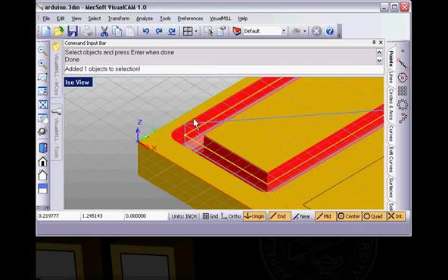If I click off to the side a little bit, this orange line indicates this is my original drawing line. So notice an engraving piece puts half of the cutter on each side of the engraving line. So if I've drawn a box 2 inches by 2 inches and engrave around it, I end up with a box on the inside that is actually smaller than my drawing. So this is a big thing to keep in mind. Engraving follows the line with the center of the tool.